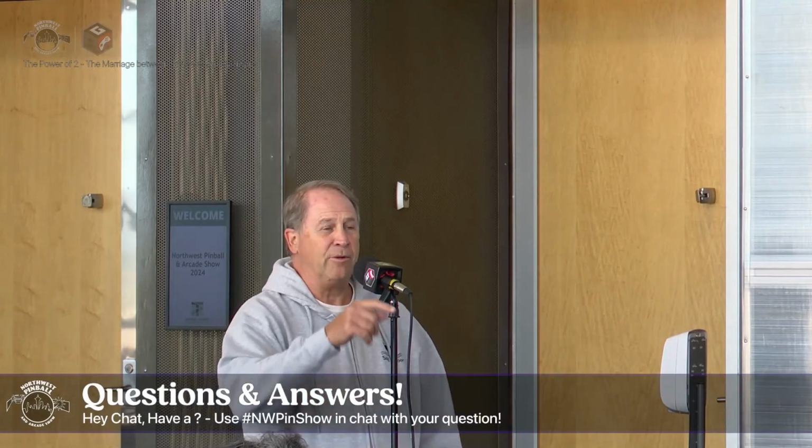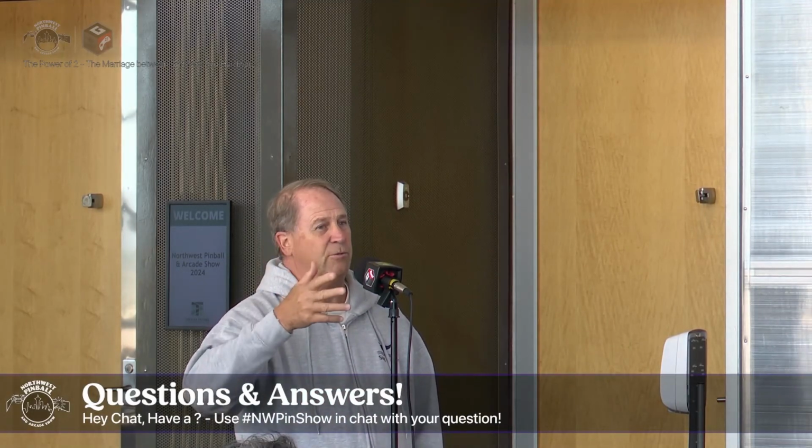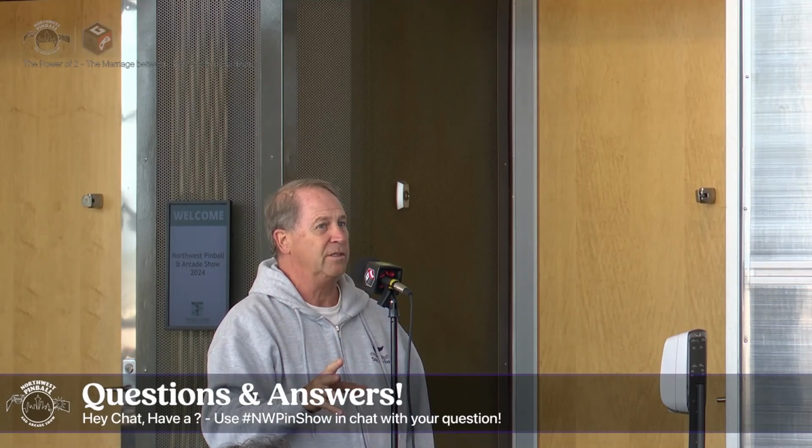Follow up on the reset. When it goes into reset condition, does it also typically work in a system that it clears registers and flags, or does it leave those alone? So when a processor comes out of reset, it is always in a known state. It is a specified state. You know what it is.